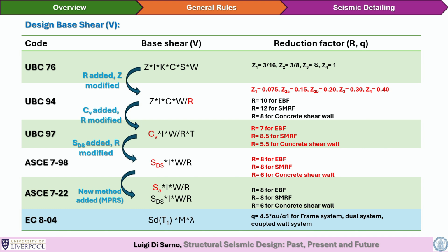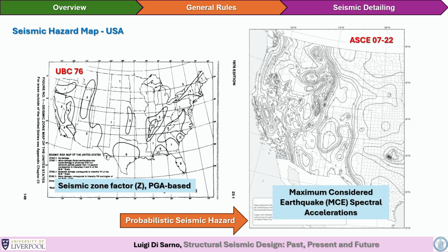If you think that nowadays there are a number of tall buildings that are in between, for example, shear walls and moment resisting frames with and without BRBs, it means that we are going towards hybrid solutions. So you will find this type of R factors implemented in a number of new codes, even in commentary, that are always very important as background information. But I would say that the most important change that we have observed in the last 30 years has been based primarily on the change of the seismic zonation.